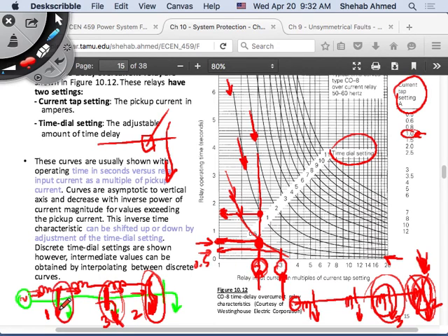Let's say the one here can back up these two and operate even after that for a fault current of 2 amps. But for a higher fault current, a fault current here would be, let's say, 5 amps. For the higher fault current, this relay here will operate also in a short period of time. Right? You see the benefits of, so this is called coordination. You put relays or fuses or breakers and you coordinate them. Right? So you have to coordinate them because one has to back up the other in the radial system.